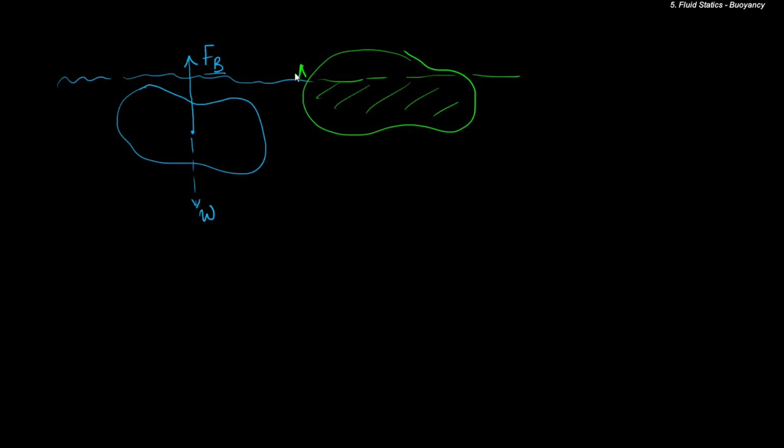So in this case, the buoyancy is because of the submerged volume that lies below the water line. So this particular line is called the water line. That is the perimeter that you see, and whatever is submerged below is responsible for the force due to buoyancy acting at the center of buoyancy, that is the centroid of the volume, while the weight acts as it is.